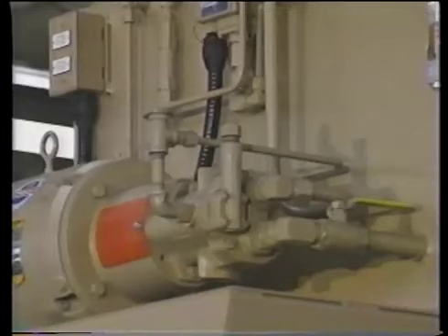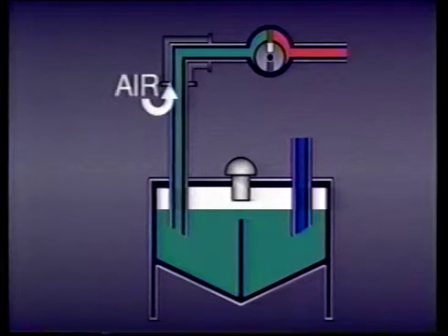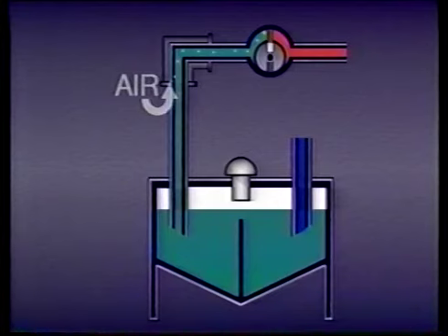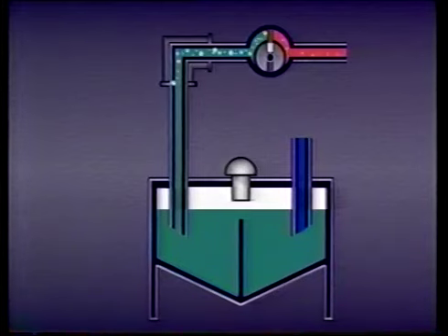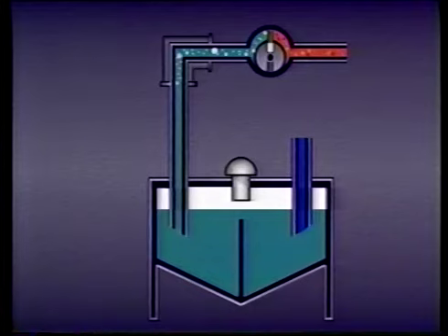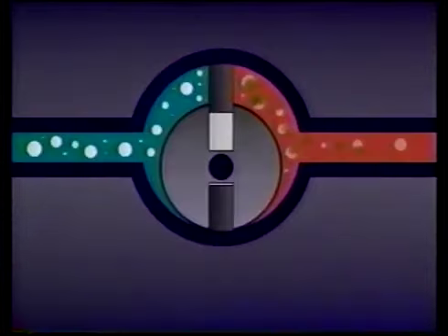Oxidation inhibitors can be added to the oil to slow the oxidation process in the reservoir. However, oxidation inhibitors have little effect when oxidation occurs at the outlet side of a hydraulic pump. Oxidation in the pump happens when air is allowed to enter the suction line through a leak or by excessive churning of the oil in the reservoir. In either case, the air forms bubbles which collapse when they are subjected to the high pressure at the pump outlet.